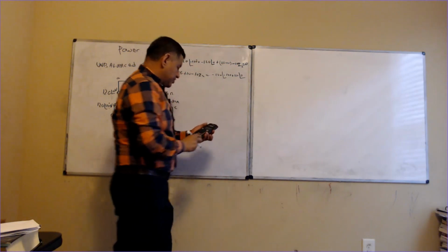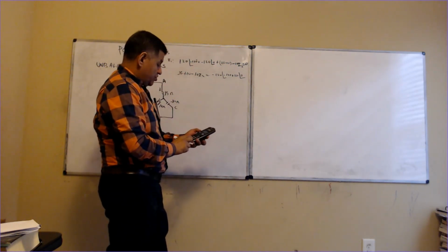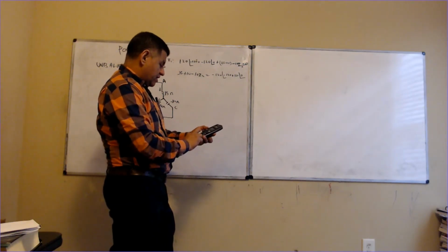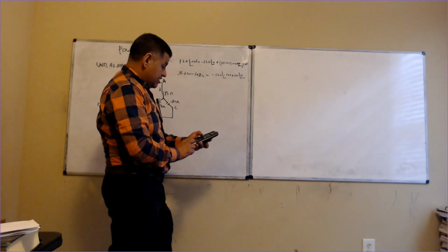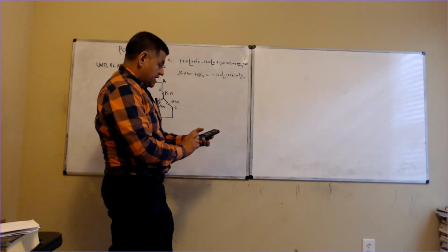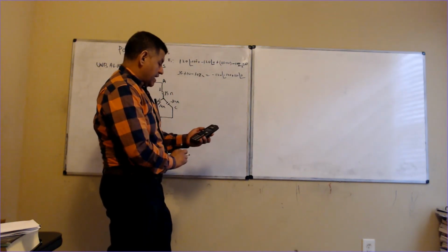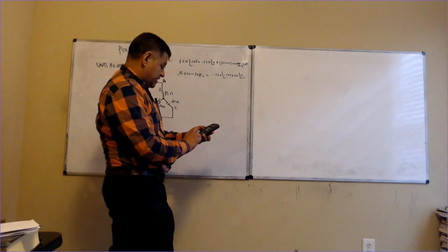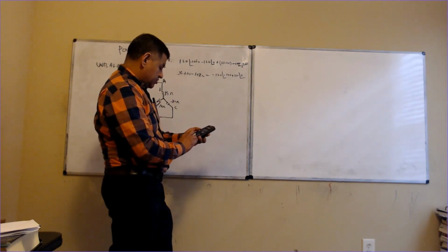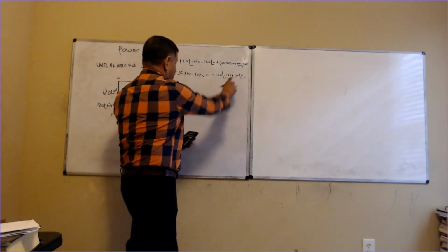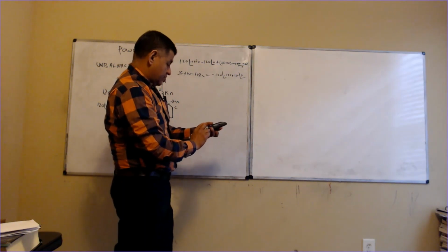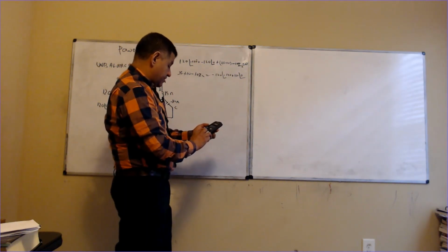So you put that into, you do second. So you put 100, negative 100, negative 120 first, right? And then you go second, and then you go complex mode, and then it's going to be an actual for angle, and you put negative 120 degrees, right? And then you put a plus in there, and then you put 120, again, that's a positive 120, and then you do second, and then you do complex, and then you do 0 degrees right there.